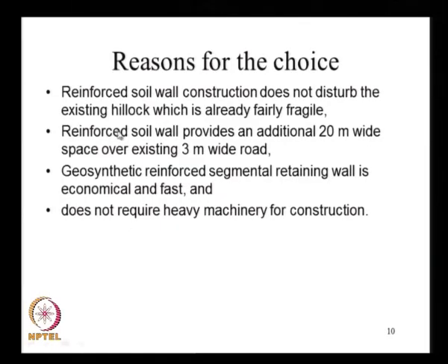This reinforced soil wall can be constructed fairly steeply, at near vertical angles, and it can provide an additional 20 meter wide space over the existing 3 meter wide road, and that is an advantage for us to create a very large